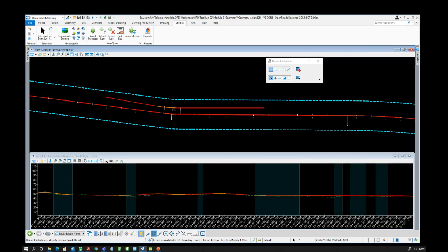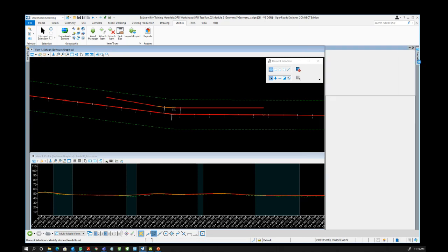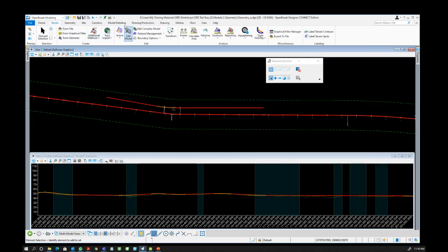But you can modify that boundary anytime you wish. If, let's say, for instance, you have a CAD line or a shape to dictate the boundary, that's also possible, because we have some tools that will allow you to do that. You see here, there are these options, especially this one, boundary options. Okay, you want to set your new terrain boundary, you can use this. Okay. Undo button is here, up here.